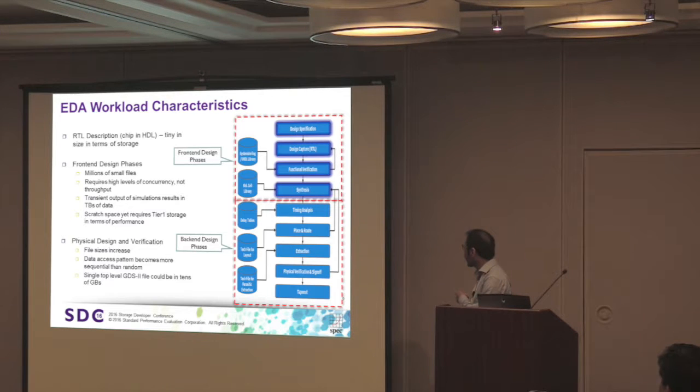You're compiling your design against a given set of standard libraries, standard cell libraries that the foundries give you, like TSMCs of the world. These are the manufacturers of the chip, right? So once you compile the design, there is more due diligence to be done. Laws of physics kick in, and you would need to do timing analysis, right? If you had, I simplified it and I said adder, but if you had cascaded blocks in your complex chip, then it's important that block A feeding into block B is not delayed. So that's where timing analysis comes in.